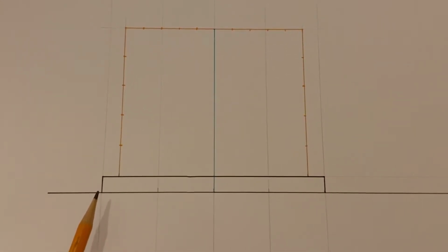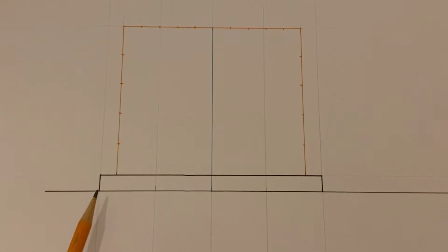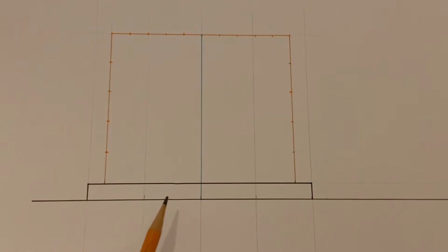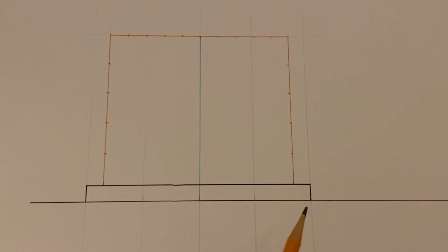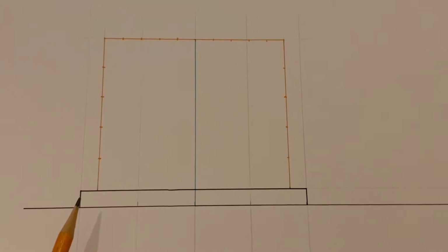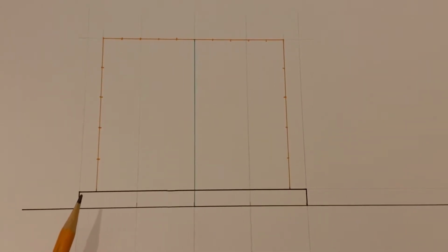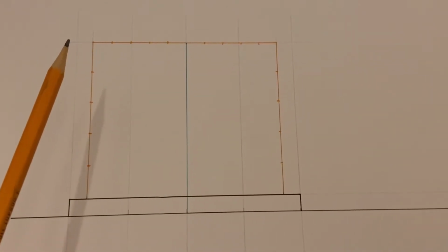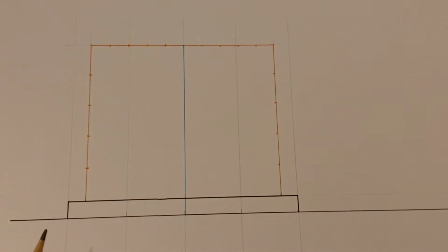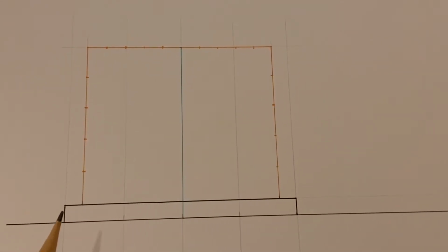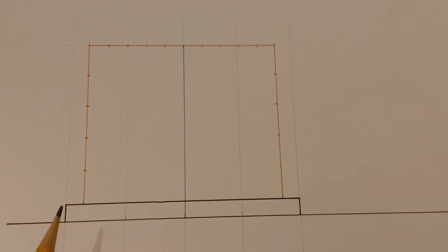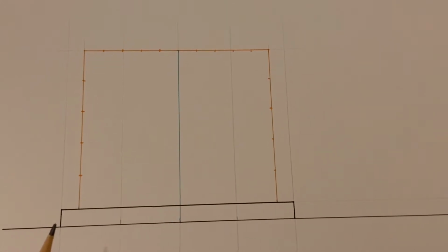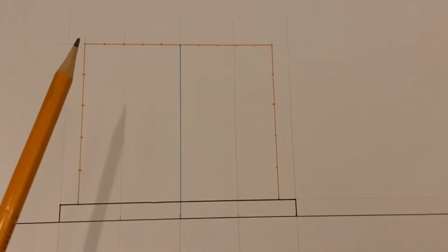Looking at the dimensions given in the question, I've measured over 35 millimeters, then 70, and I've broken that down into 35 and 35 and another 35. Again, be careful when you're looking at the question. When you're setting up, the overall height from the bottom to the top here is 110, and this bit here is 10 millimeters as well. So it's important to mark that 10 and then not to mark up another 110, because that makes the question wrong. So it's up 10 and then 100.